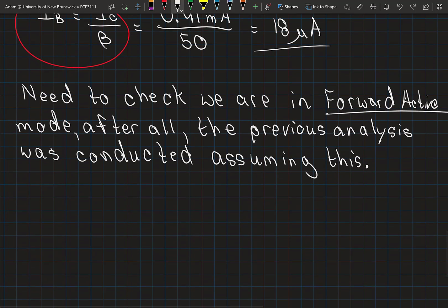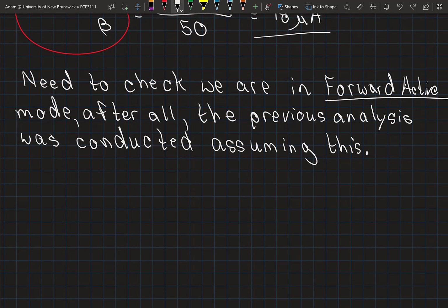Okay, so let's return to, let's just show the bipolar junction transistor itself from the circuit. And if I'm representing each of these junctions using just a diode model, this is essentially what each of these junctions is being represented as. This is representing the base to collector junction, which I'm hoping is reverse biased. This is representing my base to emitter junction, which I'm hoping is forward biased in order to have the device operating in forward active mode.